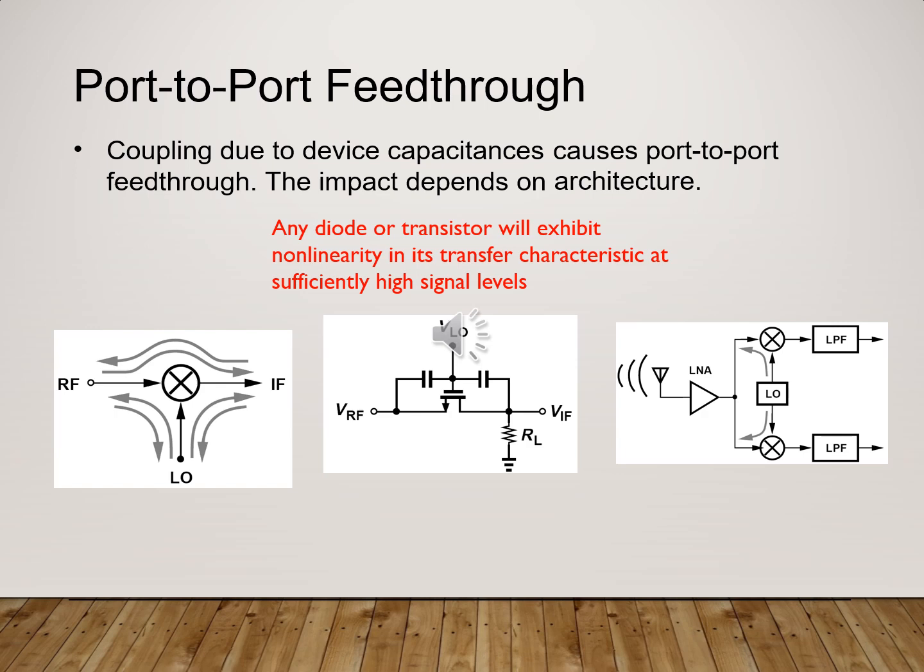The more isolation a mixer provides, the lower the amount of feed-through it will have. Isolation is measured at the same frequency as the stimulus, not the converted or shifted frequency. Therefore, frequency offset capability is not necessary for these measurements.